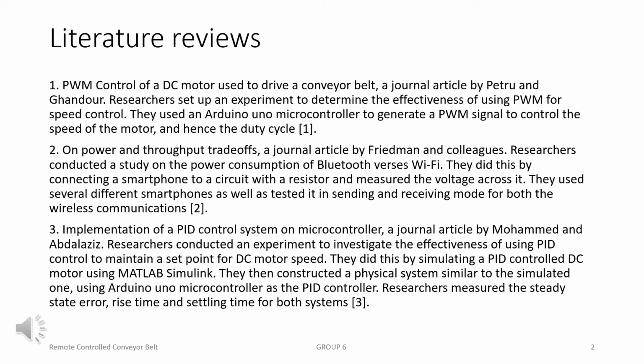They found that the data transfer rate was much higher for Wi-Fi. However, this resulted in a power consumption almost 2 to 3 times that of Bluetooth. Hence, Bluetooth was seen favorable for our application.